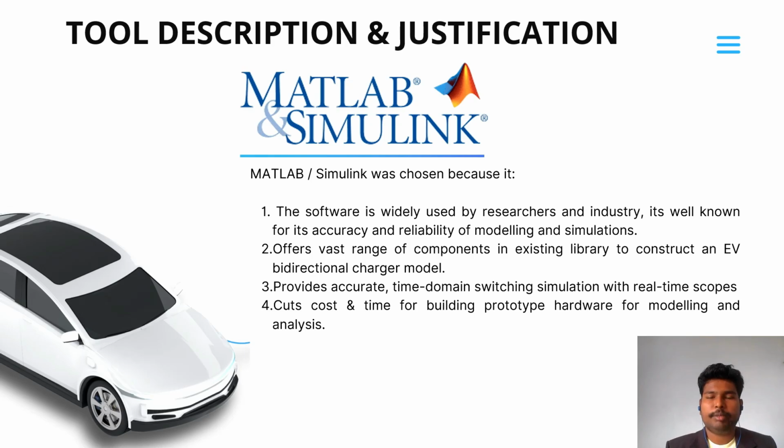So why is MATLAB Simulink chosen? First of all, the software is widely used by researchers and industry. It's well known for its accuracy and reliability of modeling and simulations. Second, it offers a vast range of components in existing libraries to construct an EV bidirectional charger model. Third, it provides accurate time domain switching simulation with real-time scopes. Fourth, it cuts costs and time for building prototype hardware for modeling and analysis.